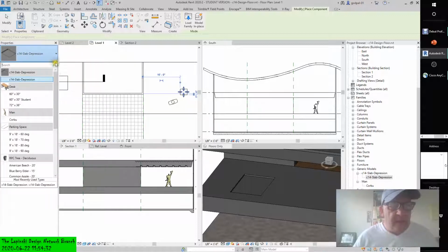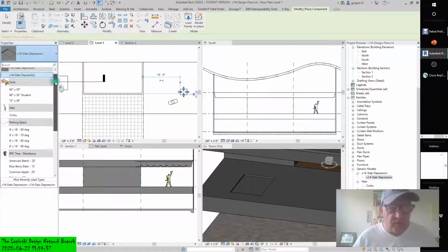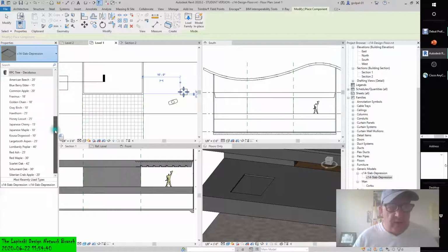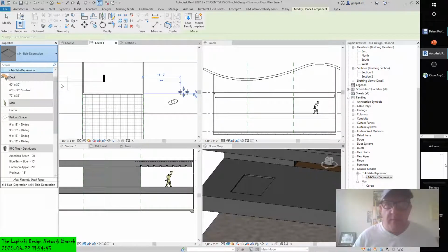If you look, it comes in under where the furniture and some of the other generic models are in place, landscaping. It just so happens to be built that way as a family. The family category is important because that's where it's going to place it within the family hierarchy. And if it's the wrong category trying to go in from a discipline that you're inserting, you get an error message, wrong family. So it's a pain, but when you get to that in the next chapter, you have to create your families with these parameters, or they'll be a bit off kilter.